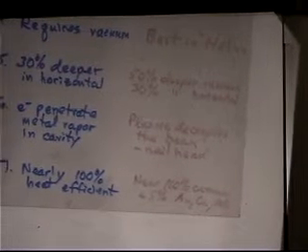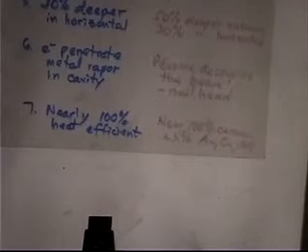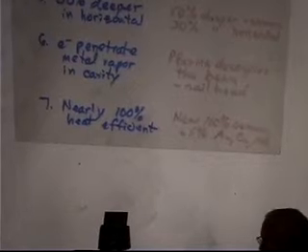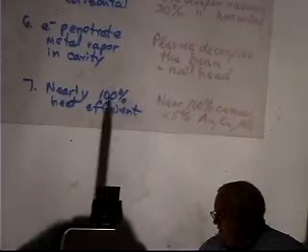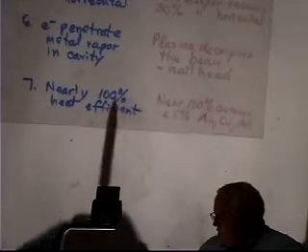Electron beam is nearly 100% heat efficient. Measurements show it at 98 to 99% efficient, because you're traveling fast and not heating up a big heat affected zone. You will create a heat affected zone on cooling, as the fused metal gives up its heat of fusion while it solidifies and the heat diffuses away. But as you're putting the weld down, you're just melting the metal. There's no time in these very high speed processes to heat up the surrounding material to any substantial amount. The actual loss is primarily a vaporization heat loss of 1 or 2%.